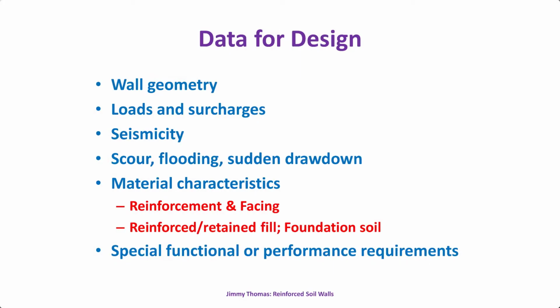Now, what are the data for design? Like the wall height, similarly loads and surcharges, especially if there could be some dead load surcharge, traffic live load. Then if it is a bridge abutment, actually the bridge loads. Then if it is a river, then scour, flooding, sudden drawdown, things like that. Then the material characteristics, reinforcement and facing, plus the reinforced fill and foundation soil.